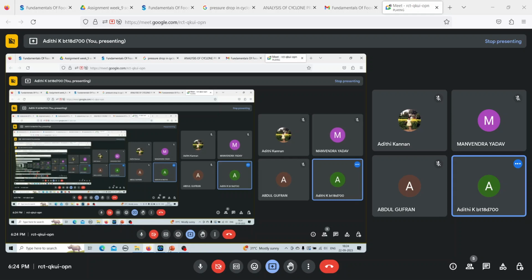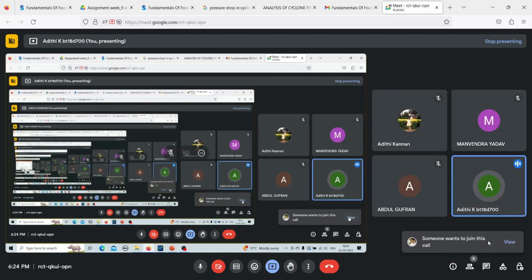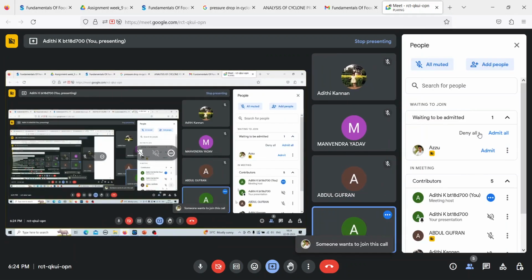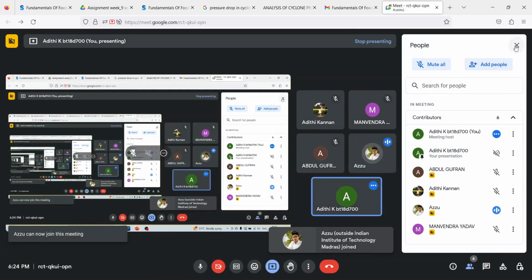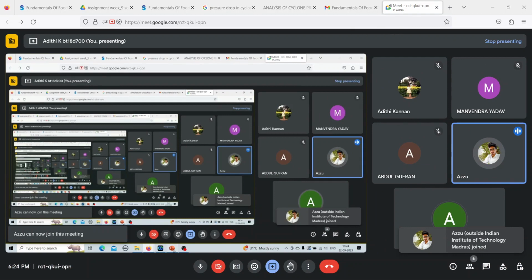The particle surfaces are smooth and the particles do not interfere with each other. If you have interference between the particles, then the forces you are counteracting, that is the gravitational force, the buoyancy and the drag force, will have an additional interference, and you cannot apply Stokes' law. The answer here is option D. All the statements above are correct about Stokes' law.